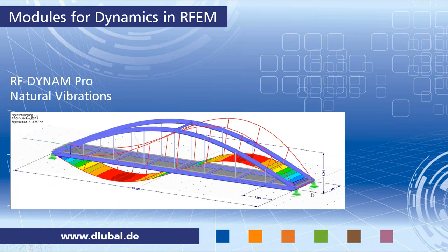...which you can use to analyze frequencies and mode shapes for member surfaces and solid models. You can directly import the masses from load cases. You can combine these mass cases in mass combinations. You can also import stiffness modifications, for example to consider the pre-stress of cables, or you can deactivate some members. You could consider the stiffness from RF-Concrete, and so on. So this is considered as initial conditions.